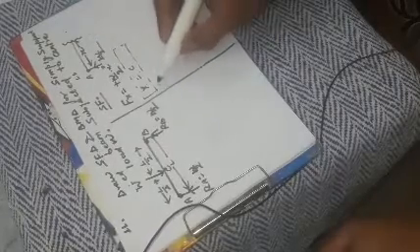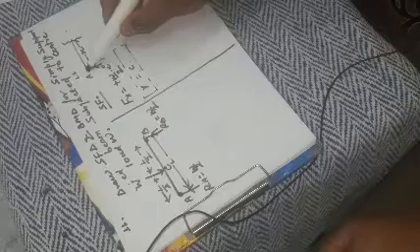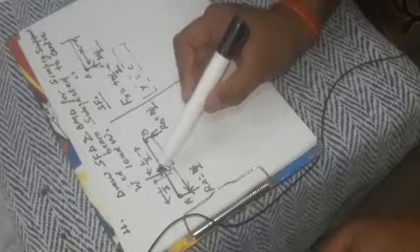Now we can say we are moving from left to right. So for point A, the value of x is 0, and segment is here just left of C. So for x equal to L by 2 at point C, and for x equal to 0, Fa equal to W by 2, and for x equal to L by 2, Fc equal to W by 2.